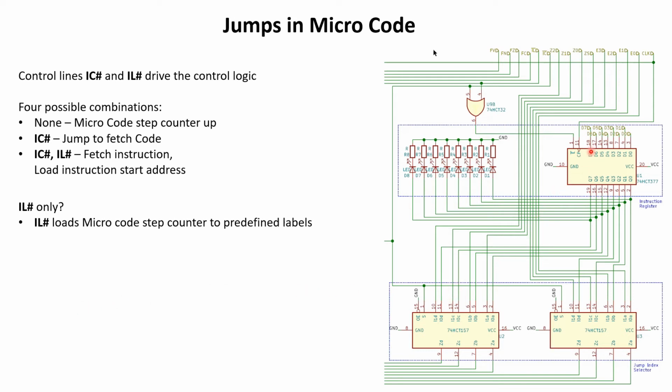It's implemented on the hardware side with 2 multiplexers, which allow switching between a byte that is in the instruction register and a byte which is specified by 8 control lines, and these 8 control lines are just reused from existing control lines.